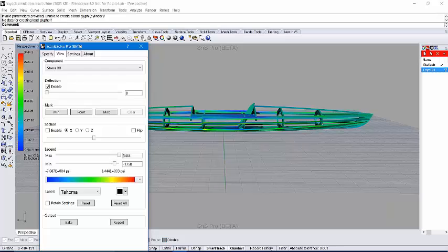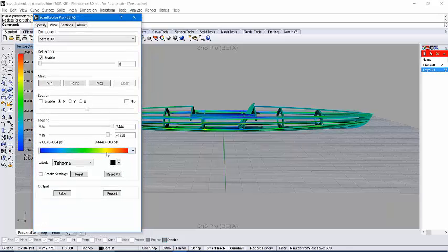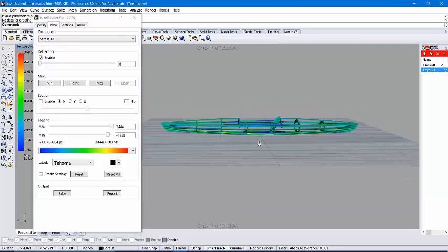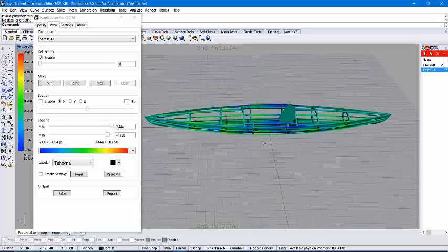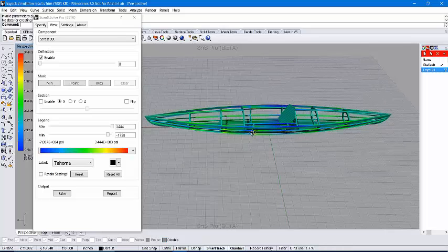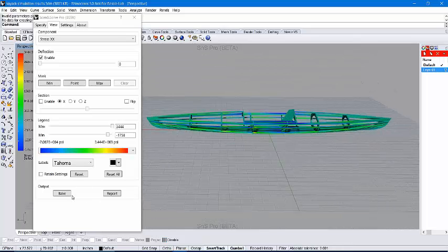The last two things I want to touch on are the bake option and the report option. So the report, if you're not familiar with Scan&Solve, will put your results into an HTML. It'll bring pictures with it. It'll describe the setup, and it'll kind of just put all your results for this simulation into an HTML file, which is pretty nice. And the bake option is used to output these results.